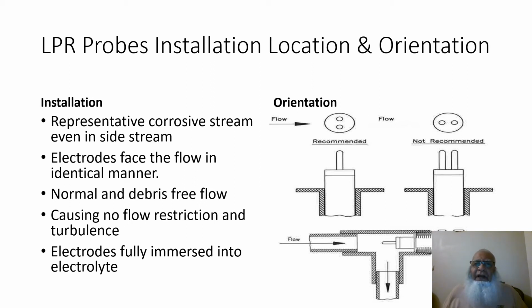In the orientation shown on the right, the recommended installation is where both electrodes face the incoming fluid flow so that they get equal impact of the fluid flow, meaning they should be installed perpendicular to the fluid flow.